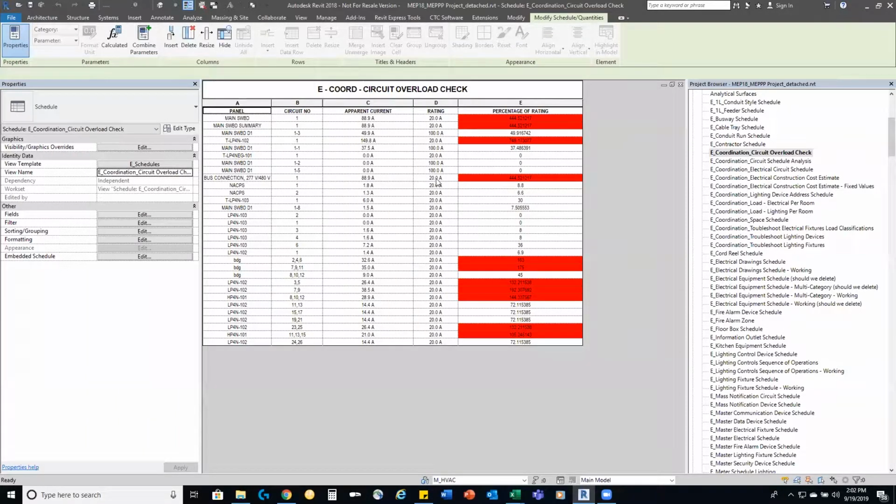So if I go ahead and look at this particular one right here, I can see I got a 20 amp breaker. I'm going to adjust this to 100 amps and see what happens. Of course, I adjusted that breaker size. That breaker size is now adjusting the panel as well, but I'm still getting my warning that I'm not quite big enough yet. So if I adjust this to maybe 110, still getting a warning telling me that my breaker is too small for 80% of the load.